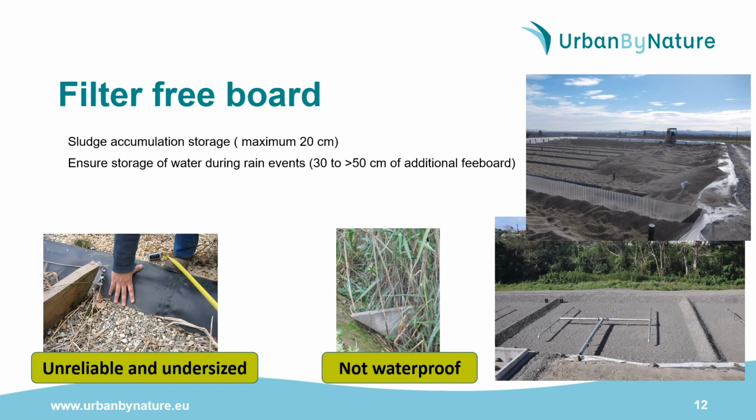Each cell of a bed must be hydraulically separated from the others by the implementation of a separation wall that could be in polycarbonate, like here on the picture, or in concrete and welded directly on the membrane. This allows a perfect resting period without any leaking from one cell to another one.